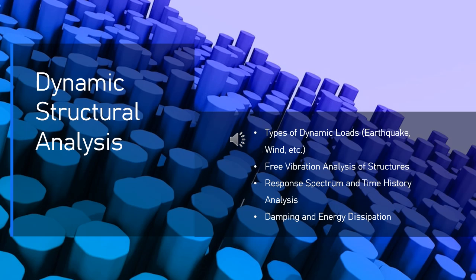Steps in free vibration analysis. 1. Formulate the mass and stiffness matrices. For a structure, we first need to derive the mass and stiffness matrices, which represent how mass and stiffness are distributed throughout the structure. These are generally done through lumped mass models for simple structures or more detailed formulations for complex systems. 2. Solve the eigenvalue problem.